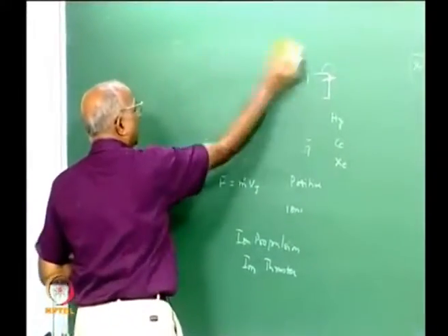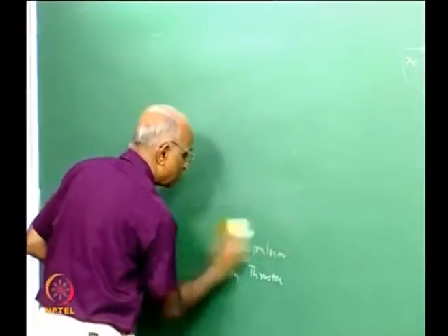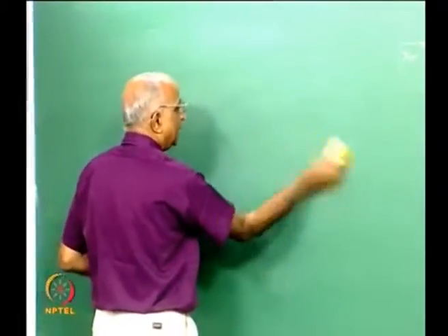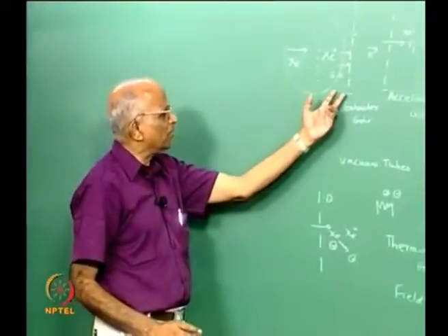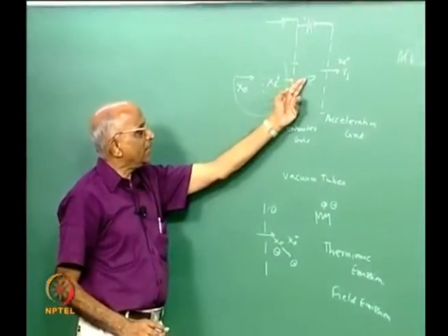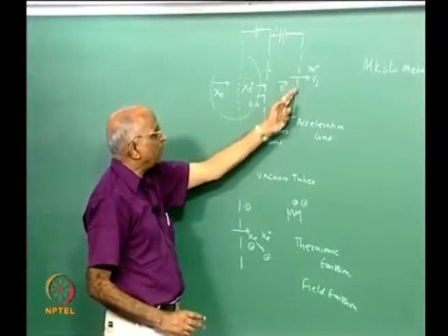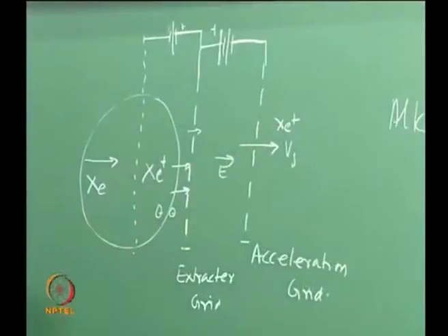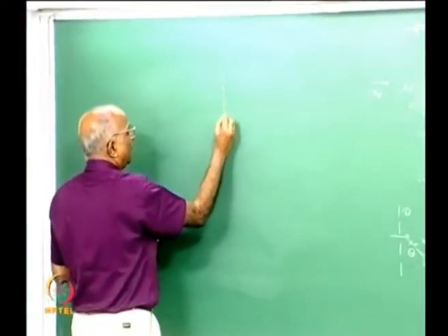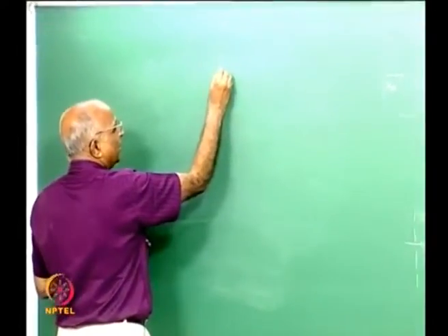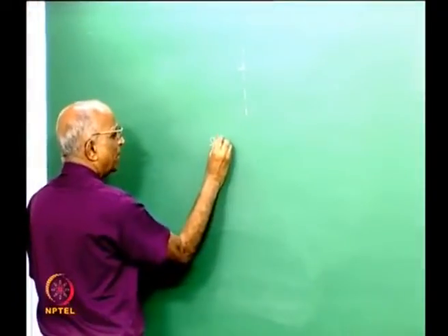Because we do not see ion propulsion being used as much as some other forms of electrical propulsion, and the reason being, let's see what are the problems. You are having these accelerated ions hitting against this particular grid, which is something like a sieve, an open thing over here, and when these things are hitting against it, it removes the metal, and this is known as sputtering.